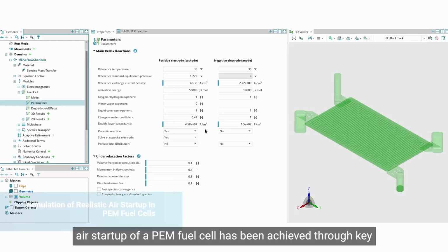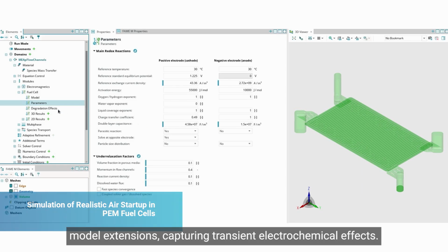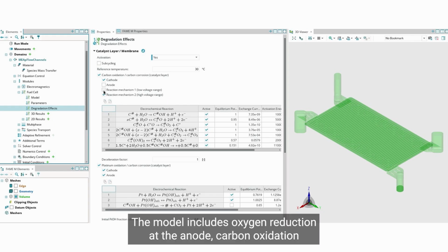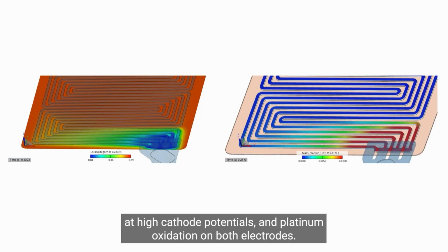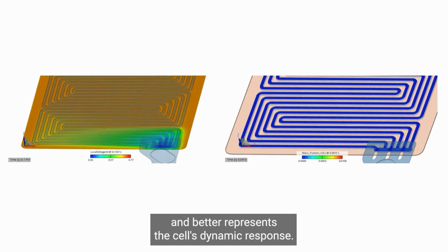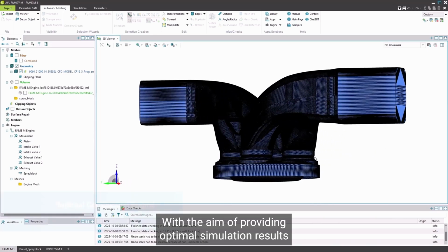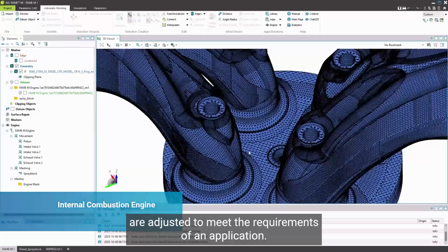A realistic air startup of a PEM fuel cell has been achieved through key model extensions, capturing transient electrochemical effects. The model includes oxygen reduction at the anode, carbon oxidation at high cathode potentials, and platinum oxidation on both electrodes. Accounting for double layer capacitance improves voltage prediction accuracy and better represents the cell's dynamic response. With the aim of providing optimal simulation results, all model parameters, but also mesh parameters, are adjusted to meet the requirements of an application.